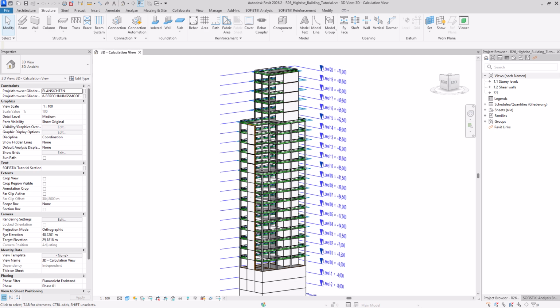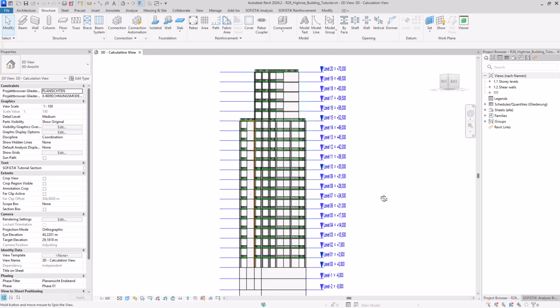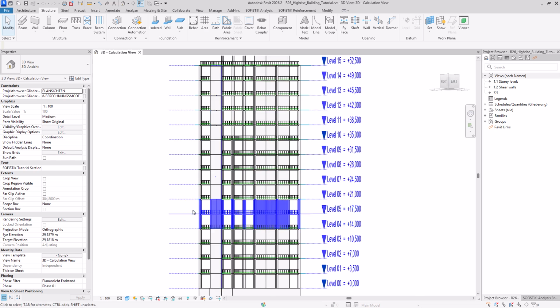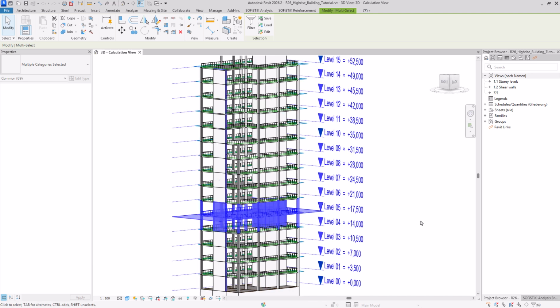For this detailed structural analysis check, we will extract a floor subsystem from one of the lower stories of the high-rise building. To ensure realistic boundary conditions, it is recommended to include the adjacent columns and walls into the floor subsystem. The usual subsystem workflow cannot be applied for a detailed check, since we will manipulate a multitude of properties which would interfere with the classical design workflow.